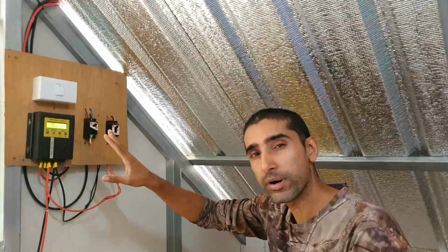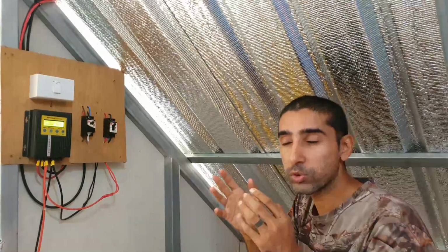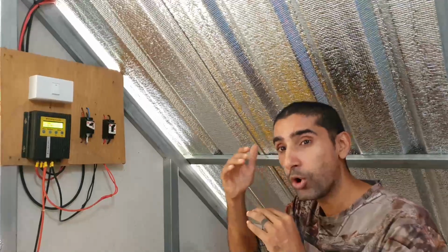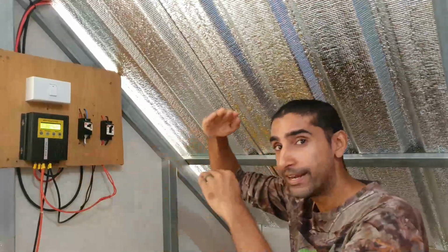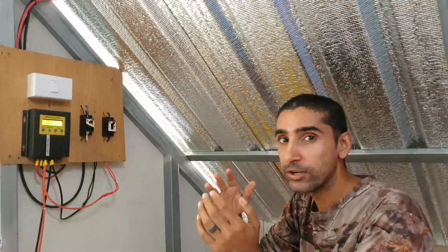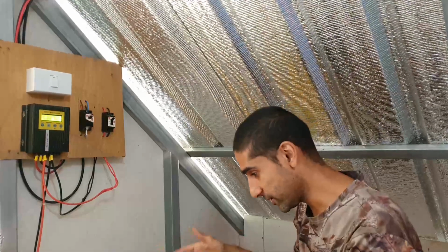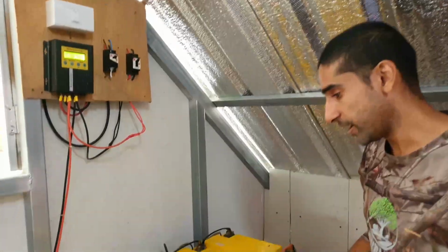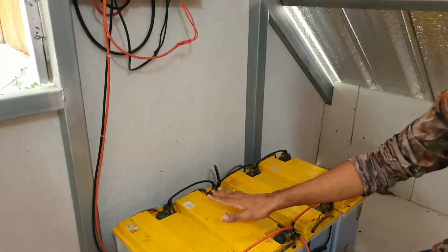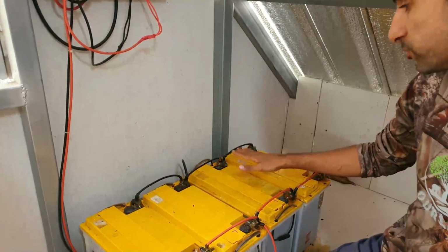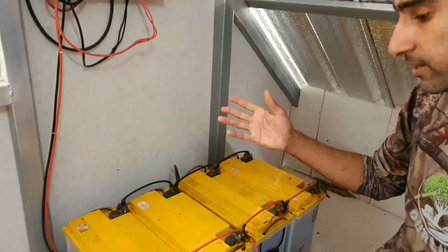Now this is very important because sometimes the solar panels will produce a lot more voltage. So your 12 volt solar panel might actually produce all the way up to 20 volts of power. It is the power management system that dials it down to between about 13 to 15 volts and feeds that into your batteries right over here, right? Now this is a very important next step because once the batteries are charged, the batteries then provide power to all the appliances inside your house.